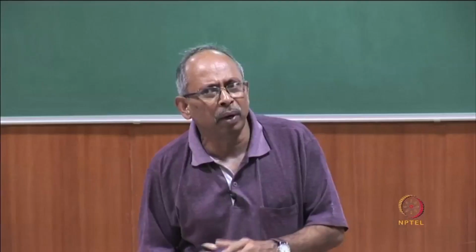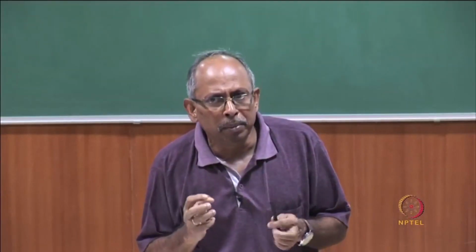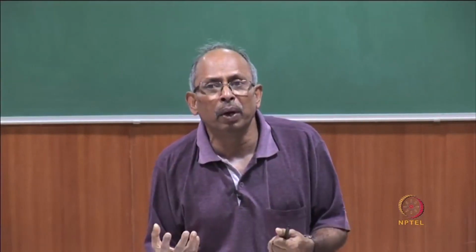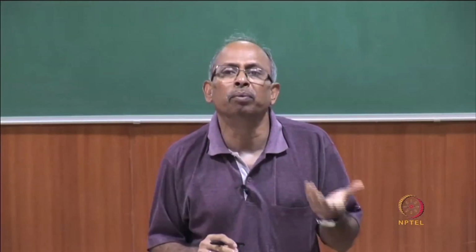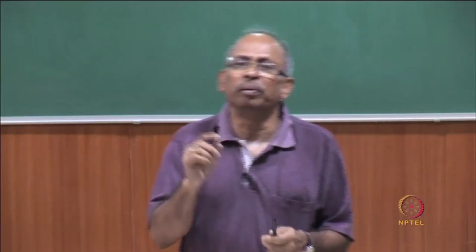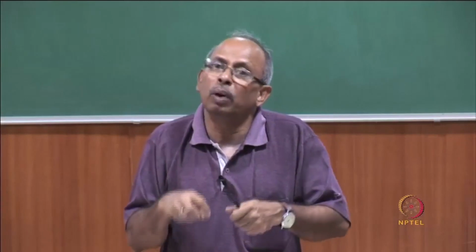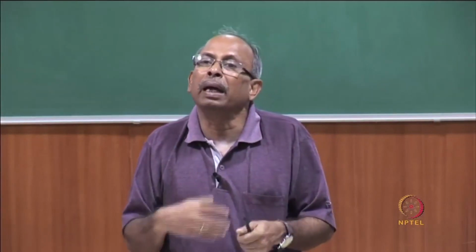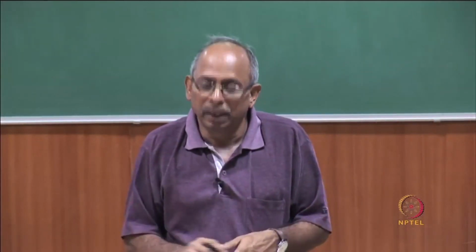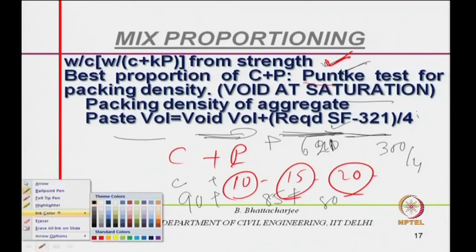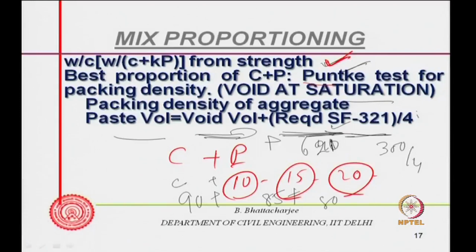All I can say at the moment is that it will depend upon the slump flow. The higher the slump flow required, the more paste volume is required, and this we have understood from the fundamentals, because it is the paste on which the aggregates will have a kind of piggyback ride in the system. Therefore, it's proportional to slump flow. The higher the slump flow required, the more paste you will require.